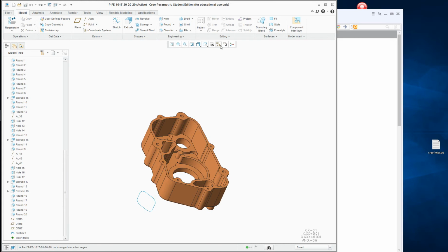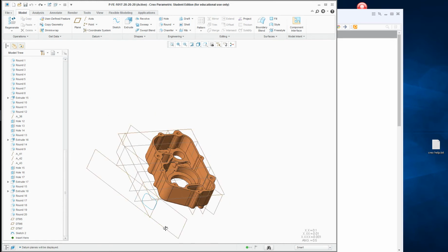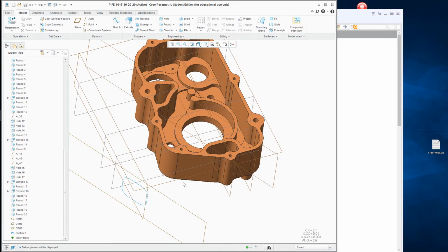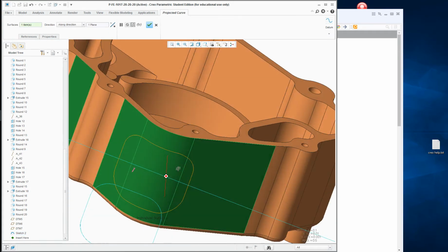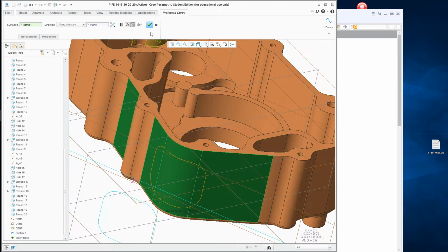First, you need to put a sketch in the plane location on where you want to send your profile to. It's not always good if it is exactly parallel and then you're projecting, because the sketch will stretch a little bit around when it's bending around corners. So pick the sketch, hit project, and then pick the surfaces you wish to throw it to. As you notice, when this thing's hitting, it's actually stretching a little bit, so it's not exactly the same radii.